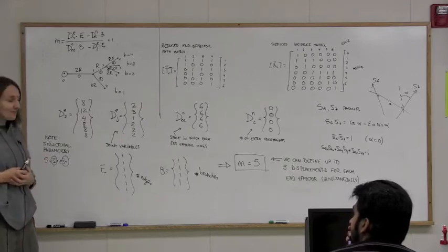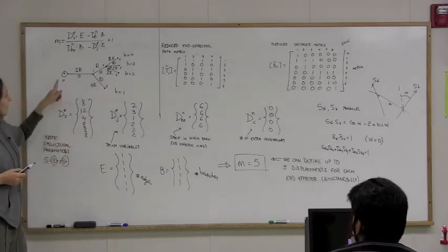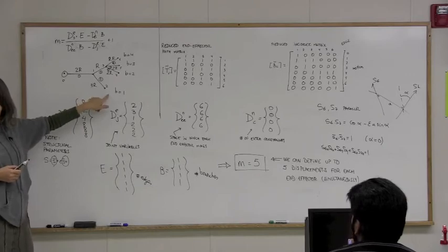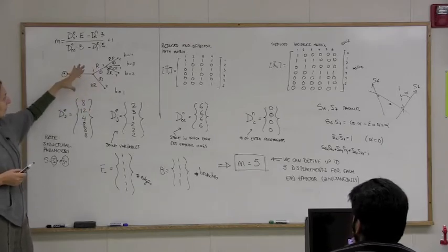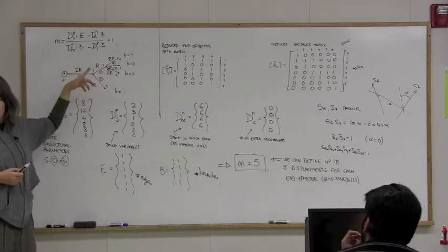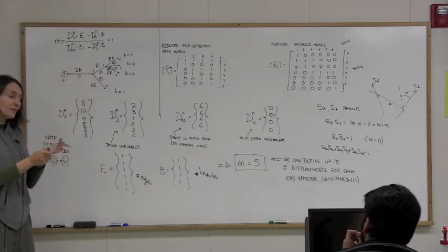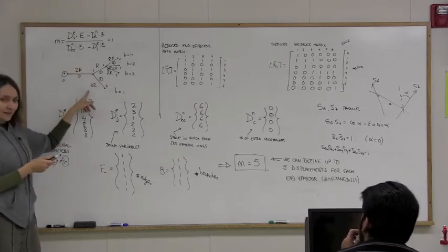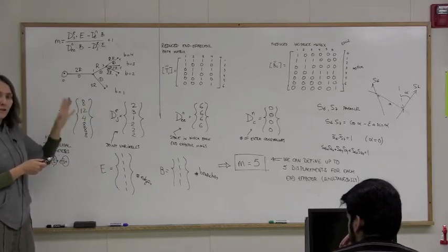Not only that, but it turns out that because now we have several end effectors, we can actually change the root. For instance, now we fix this and move all these other ones. First we were like this, and now we fix this and we move everything else. And that may change the solvability too. So we need to look at all permutations of root vertex, and then all possible subgraphs for each permutation.